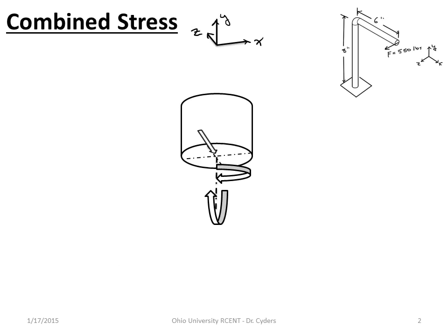So again, what we have here is a transverse force that's going to be 550 pounds in the negative z direction. Again, I'm looking up from the bottom of this 8-inch section, and we can see how we've changed our axis orientation here. So we've got a 550-pound reaction force in the opposite direction, so it's negative z. I've got a reaction torque that is going to be in the opposite direction, and according to the right-hand rule, that's going to be in positive y, my reaction.